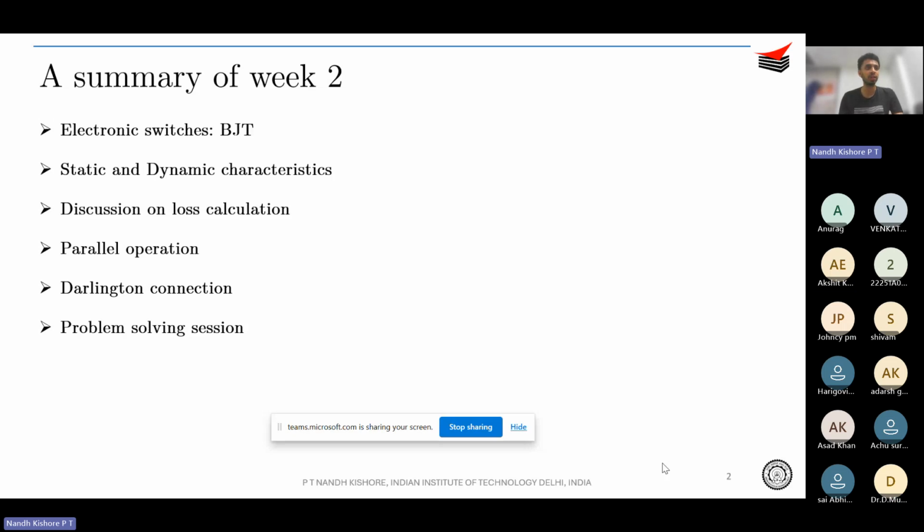And it will have an avalanche effect, wherein the device that's carrying higher current is going to carry even more current, because its effective resistance is going to decrease. So at some point of time, this device is going to carry the entire current and it may get damaged. So once this device gets damaged, the entire current will flow through the other device, and hence the other device will also get damaged. So it's going to lead to a catastrophic failure, right?